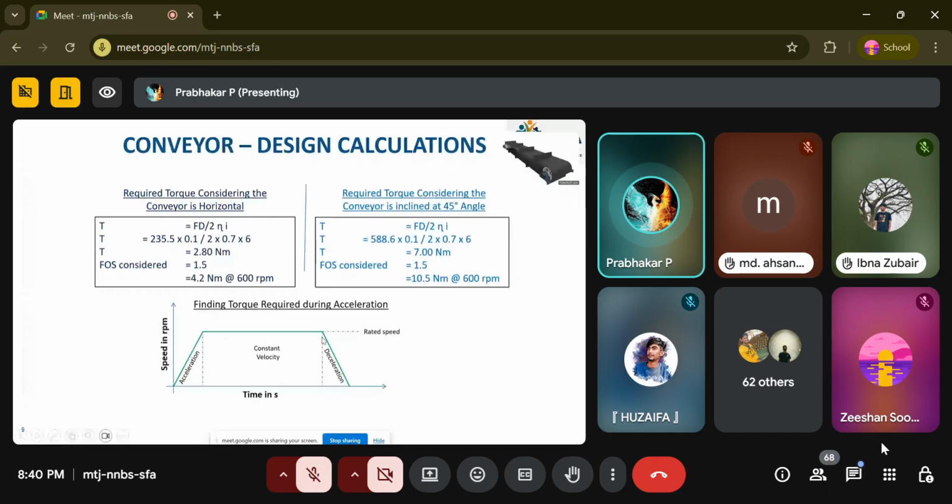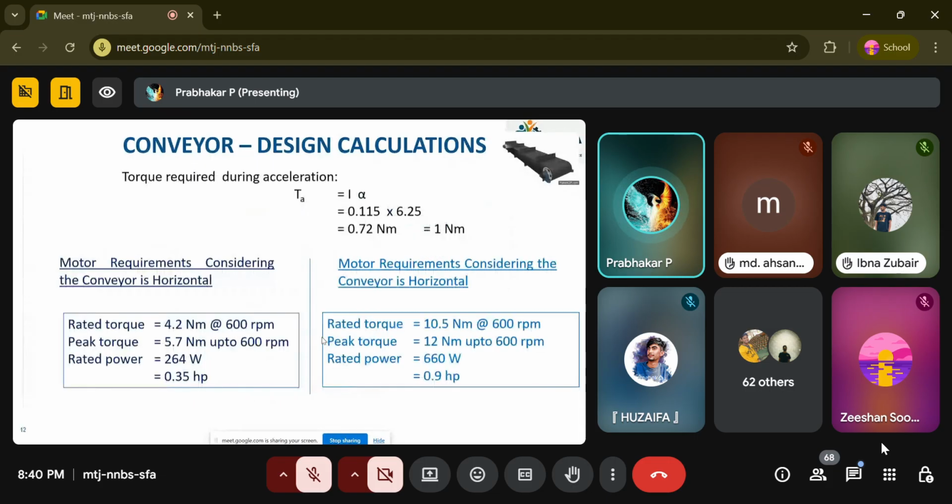One example I can give is the rotary index table. In the machine shop, in a CNC machine, the index tables are fixed for providing the 5th axis and 6th axis, where the machining is done. It has to stop precisely so that you can machine, sometimes with 10 microns or 20 microns accuracy, at a precise position. In those areas, servo motors are used, where the precise start-stop is needed.